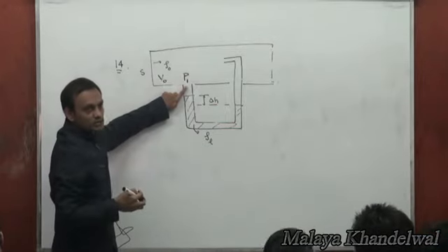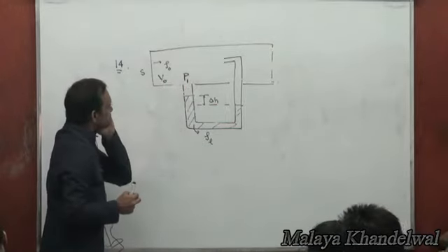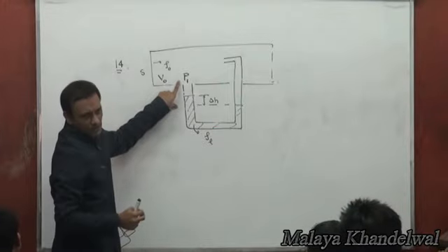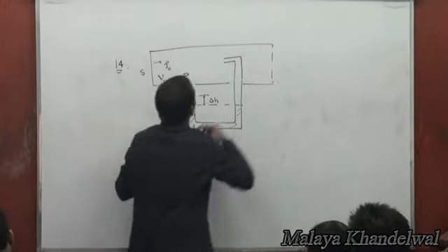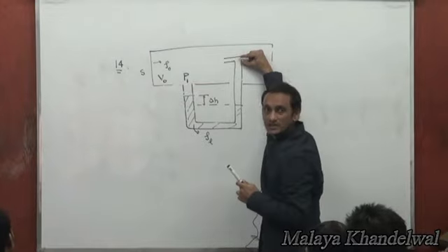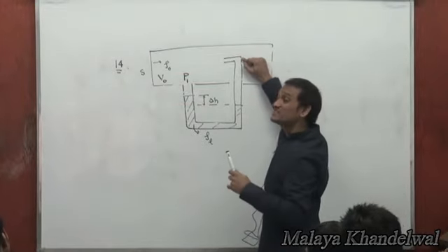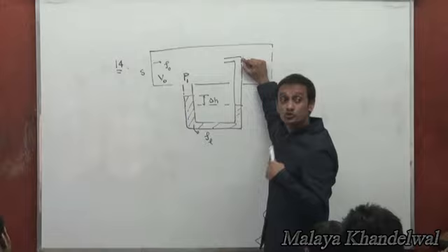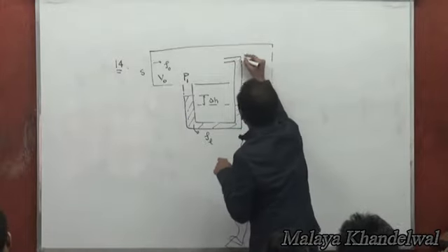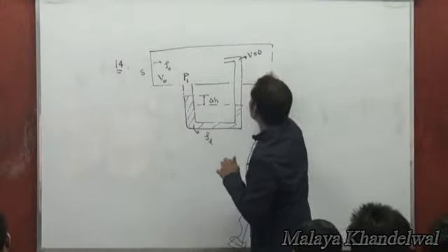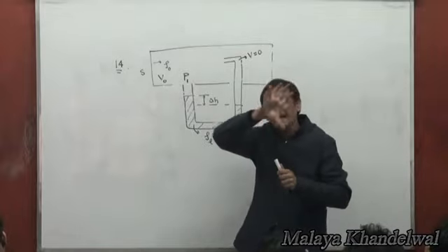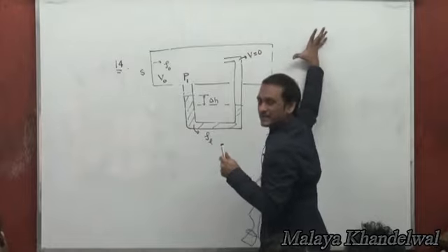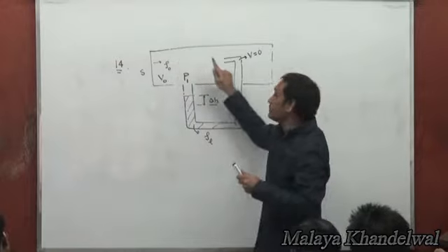Just above this limb, the pressure is P1, and the velocity obviously would be V naught. Now, when a sample is inducted in, it strikes this wall and comes to rest. So the flow has 0 velocity here. Same datum though, because this is a thin pipe, so the same Z.